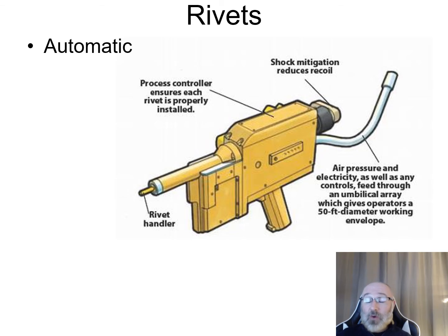Now with those manual rivets, that's quite a bit of work. You definitely need the set. You need the skills, the knowledge to know how to use these, and the experience to get it just right, to get the right amount of force on that. Again, you're manually hammering this in, making the shape so it fits in the set just right, and then compressing it to get that perfect dome shape at the end. You want to make sure it's compressed just enough to hold those two materials together.